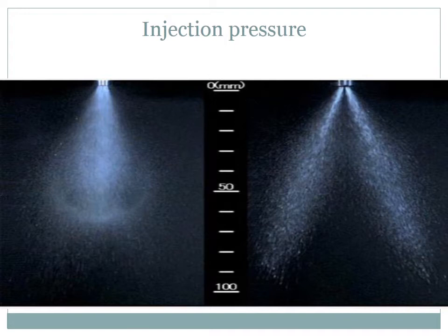But in the right image we can see the injection of fuel occurring at high pressure, so it will cover more crevice area inside the cylinder, so the utilization of the air fuel mixture becomes better and the combustion is complete.